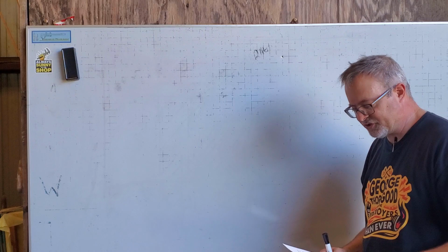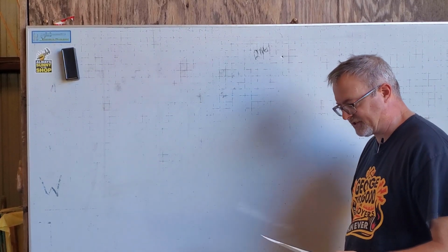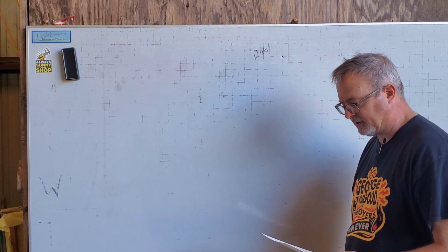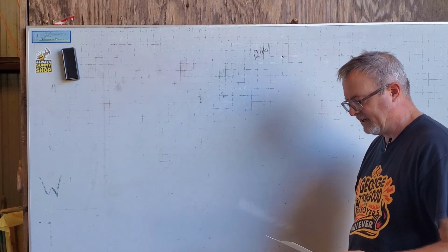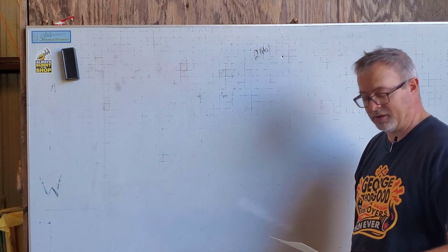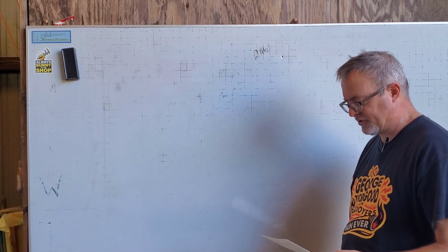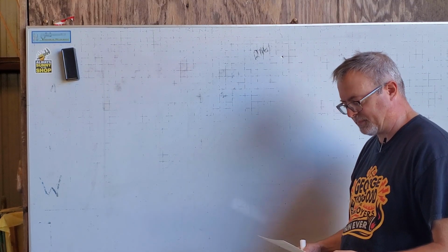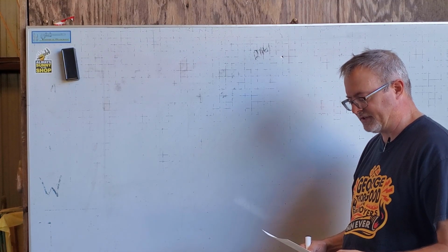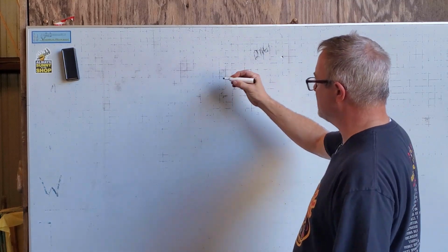So Casting Iron Engines writes, I have read a number of the old steam engine design books, and while I understand steam engine dynamics better than I did initially, I still don't feel like I have a complete understanding of all the forces and power transfer involved. A few things I have read, check me on all of these. Number one, most of the work occurs in the first quadrant, i.e. from a crank position with the piston at top dead center to a crank at 90 degrees. Correct. Now there's a little bit more to that than meets the eye.